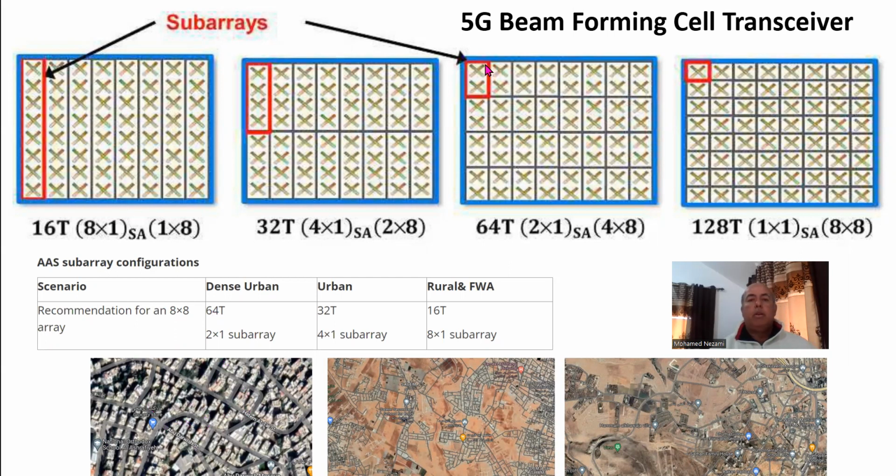That's where we would narrow the beam. Unlike this, we don't use 1 transmitter driving 8 antennas. We use 2 antennas, 2 transmit, 2 receives on each polarization, and then we can have many of these, and that would be 64 of them in this case. This is an example of a 28. So that's a different situation.